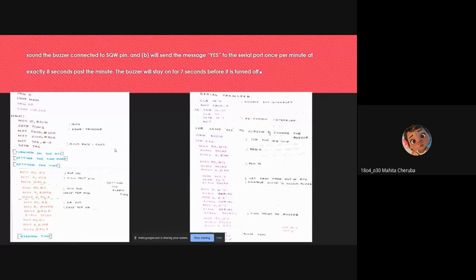And in the interrupt service routine, we are initializing our register C, calling the delay, and again moving the data into our register C, and we follow the same thing for register B.